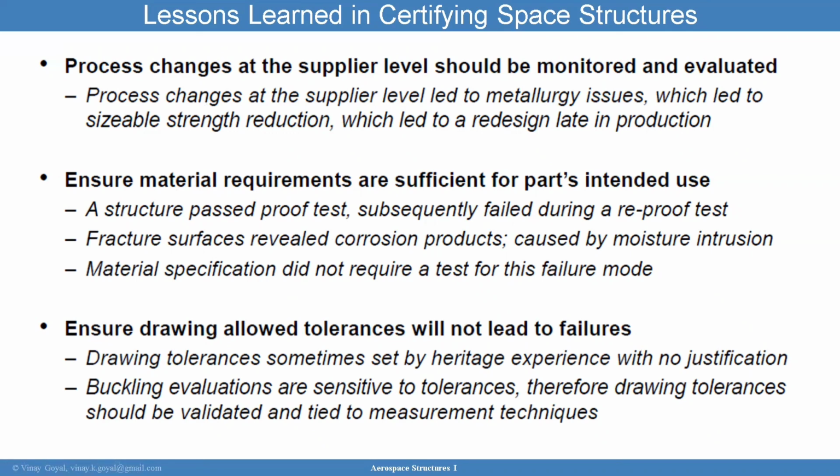Sometimes they're based on experience. But you want to make sure that the drawing tolerances are not such that, because remember, the analysis is done with nominal drawing tolerances. But if your drawing tolerances allow for more variations, the tolerances in the drawings could be a problem. So say the thickness is allowed to go down to 10 mils. Well, you want to make sure your analysis can survive that.